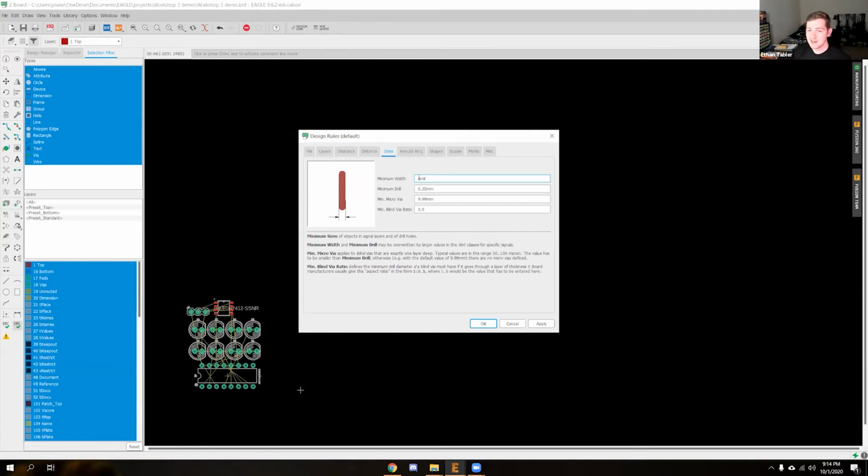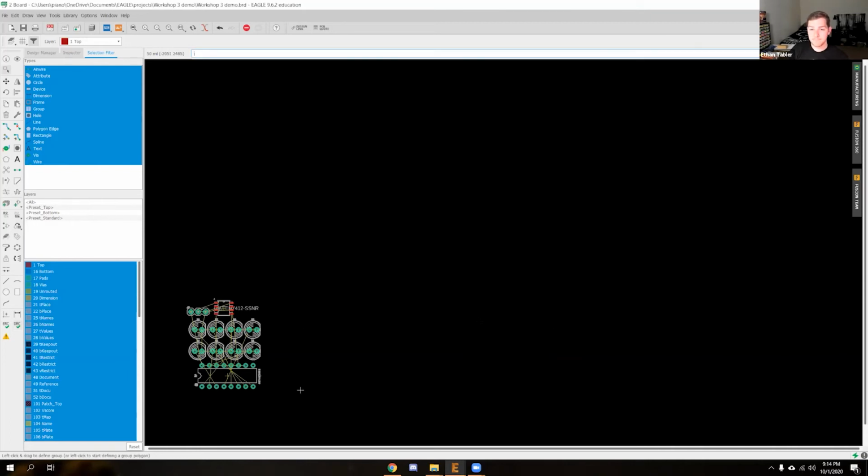Does everybody see the 6 mil in the top category? Okay, go ahead and change that to 10. Hit apply, and then hit OK. Should close that window. So that just beefs up the size of the tiny little wires or traces that are going to be on the PCB.